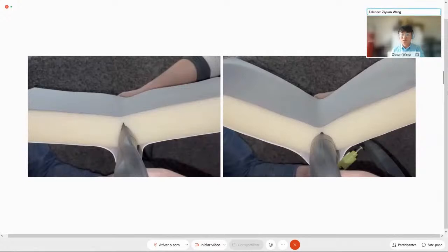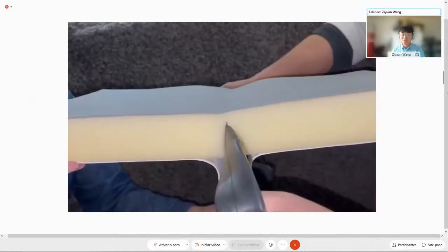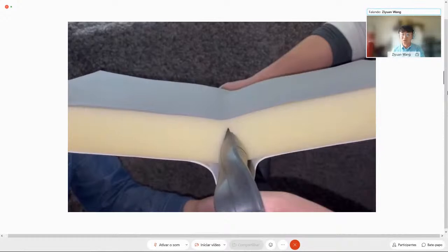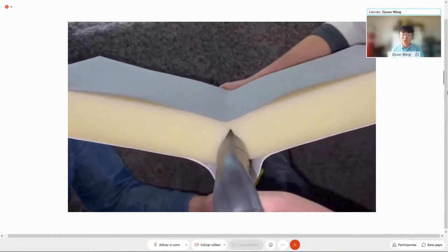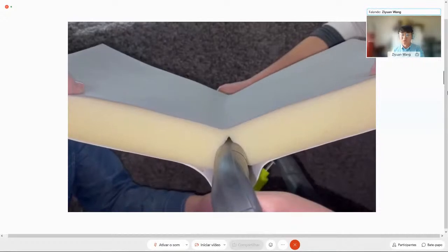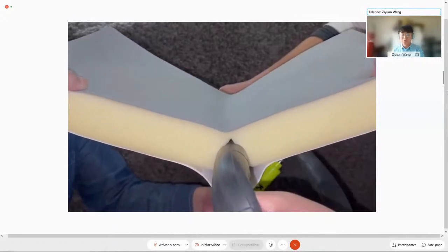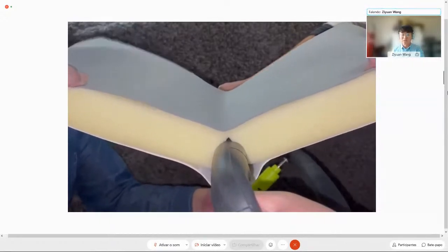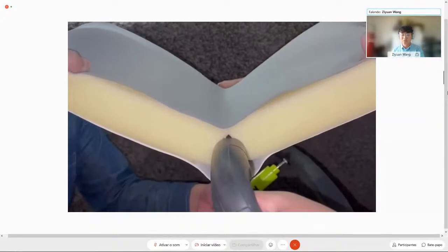To verify this, we used sponge and an airbag to simulate this principle, and it works. We use a pump to inflate the airbag, and we can see that after pumping, the airbag pushed the sponge to deform according to our expectation. And here is a video about verifying the airbag system. Since the material in the market is not easy to find, we enlarged the model's ratio to 5:1, which means the prototype is 5 centimeters thick, where the real laminated layer is 10 millimeters.